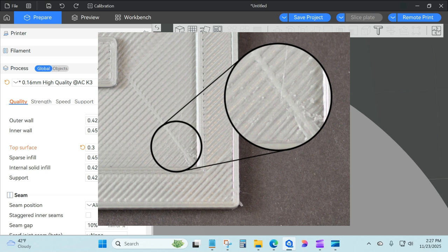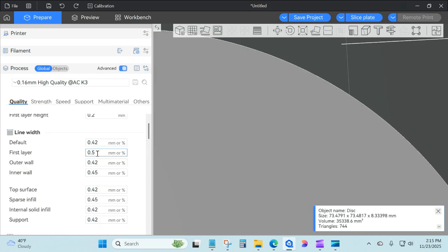You'll see people give quite a bit of advice on how to fix this. Typically, it's reduce your flow ratio, doing a calibration of your filament. Again, already linked that video. And increase your Z-hop, which, okay, sure, that's like a temporary fix, still doesn't fix the quality issue that you can visibly see that there are ridges on the top of your model, especially if it has flat surfaces. So you'll need to adjust your flow rate down or decrease your line width somewhere. All right, so that's first layer line width.